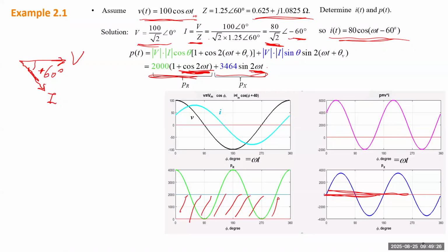Okay, so finally, this rectangular area indicates how much energy the load will consume for 1 cycle. So if you divide this area by time, that will tell you the average power. So if you treat this load as some purely resistive device, this is really the total energy the device consumes. So that's why this number is very important. They really tell you the average power of the device.